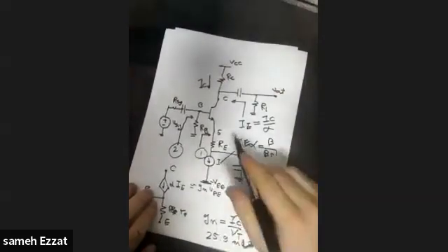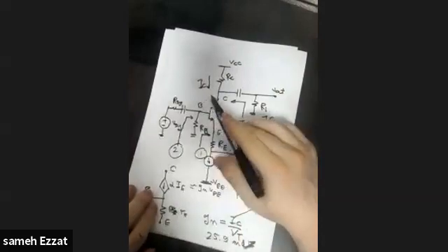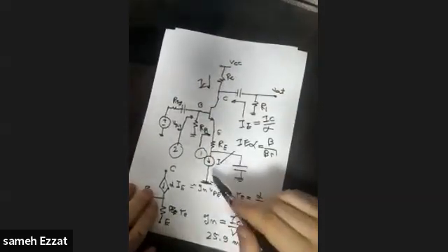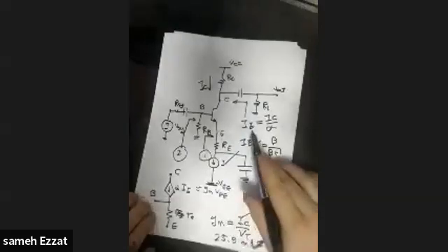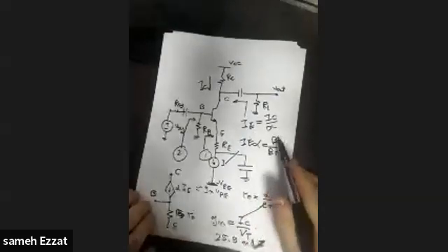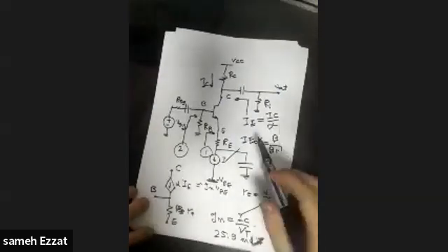So in order to calculate gm, all you need is IC. You don't need to make a full DC analysis, and you will usually be given this IC due to this current source. As far as you have this current source, you can calculate gm directly from this relation. Sometimes you can say that IE is approximately equal to IC when alpha tends to 1. For example, if beta equals 200, then alpha tends to 1, and then IE equals IC, and you can get IC directly from this relation.